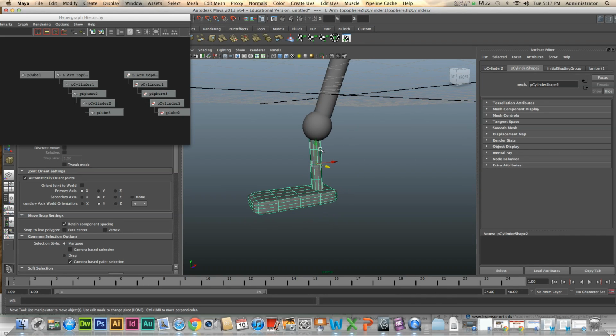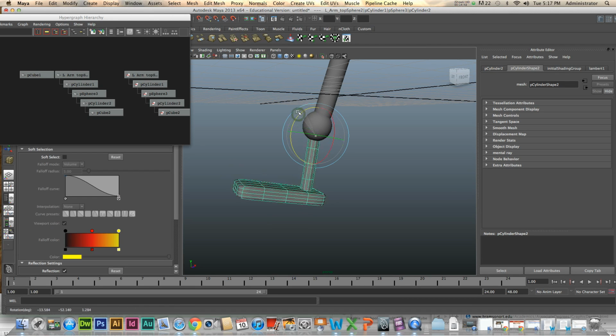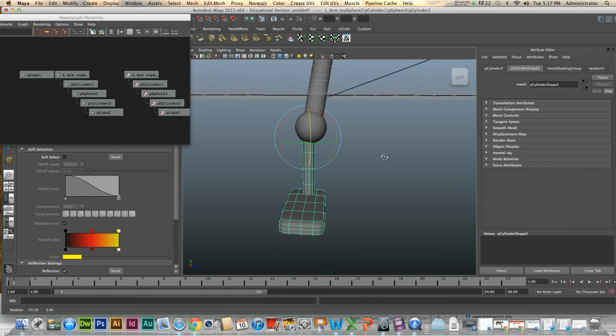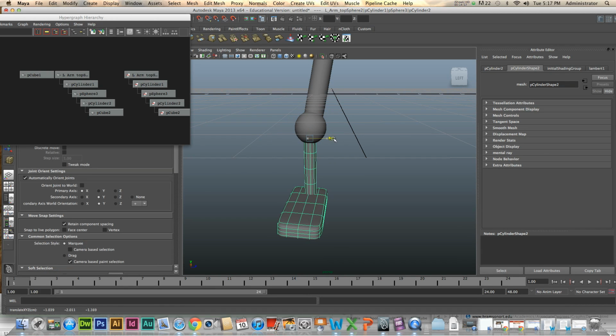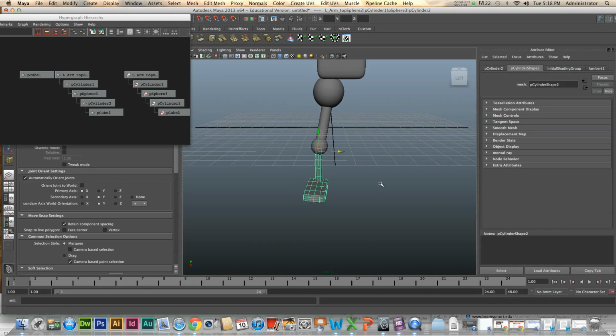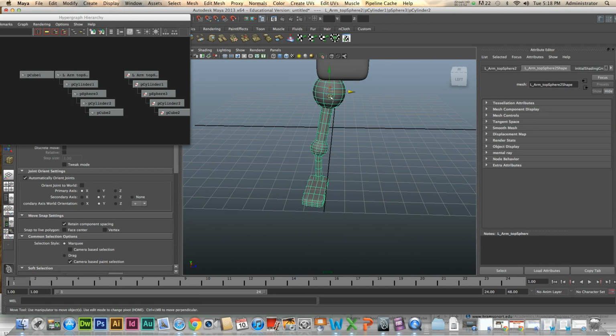Today I'm going to show you how to actually drag this pivot point to the top so that it rotates from the point where I want it to rotate from. So what I'm going to do is hold down the D button, and I'm going to go ahead and move that pivot point to the top. And now, when I press E, it moves exactly from the direction I want it to move, okay? So that's what's great about Maya, is that you can actually change your pivot points, and this allows you to choose which direction you can move or rotate certain objects from.